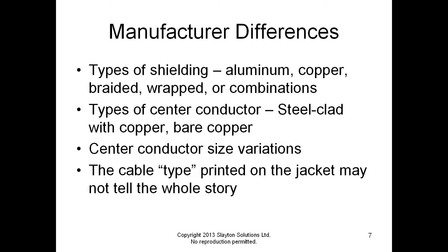Now, as I mentioned, different manufacturers are going to have built their cables different ways, and there's good cable, there's cheap cable, there's cable that came from overseas. The key here is that what's labeled on the side of the cable might say one thing, but that doesn't necessarily tell you the whole story about the cable. And I must emphasize this: you need to know the quality of the cable you're hooking up to make sure that you'll be able to push through that cable. The Ethernet, and particularly the power over Ethernet, is what becomes the issue.